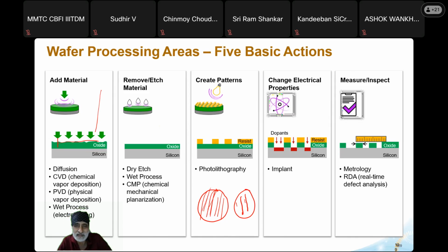Photolithography tells that in this area I have to protect these lines only, so the mask will tell. That mask information will be there in photolithography as shown here. This yellow layer was there on the entire thing, and now here it has been removed. That information is there in the mask, as shown here. And I have a mask here which you will not be able to see much. So this is one reticle, and the size of the reticle is 26 mm by 26 mm. The structure is repeated, and this is one mask. It's in a box.